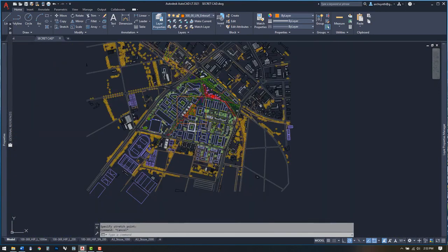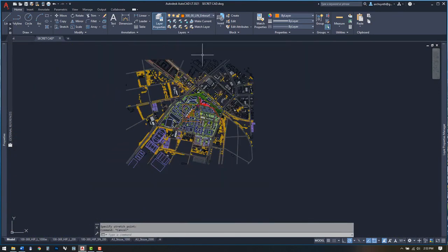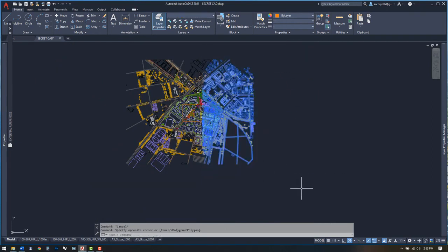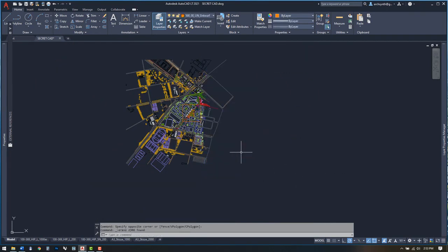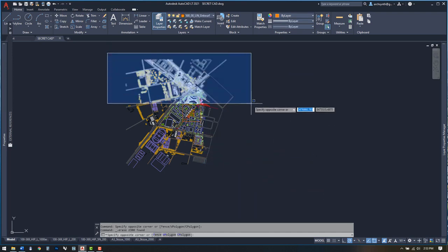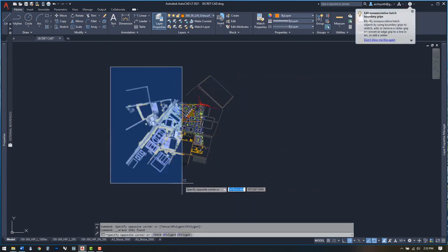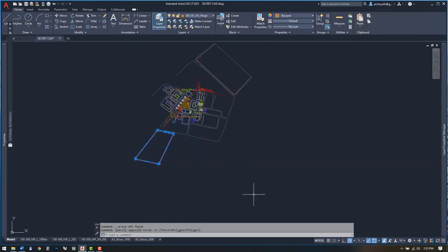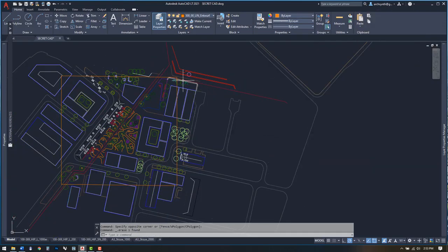After selecting our focus region, let's use the selection windows to eliminate all of the extraneous context surrounding this. It might seem aggressive, but when we're working in 3D, it's important that we keep our files as clean and as meaningful as possible. So unless we're creating large aerial views, none of this context would ever be visible and it contributes very little to the design.